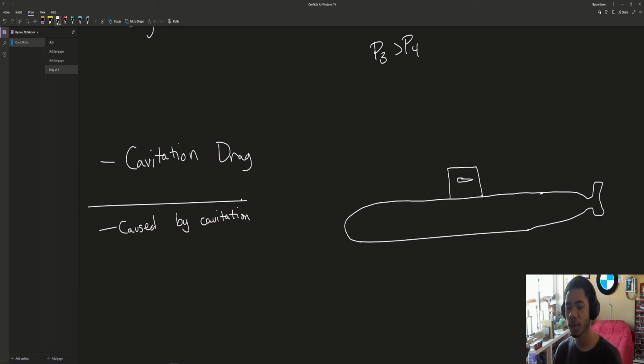Did you know that there are also airfoils on submarines? Because fluid dynamics has the same fundamental properties in water as well. That's why it's called fluid dynamics. It uses a subsonic shape for its body. So anyway, let's go ahead and get to cavitation. So cavitation is, let's say the flow is going over the sub. As the flow goes over the sub, it's going to speed up. And it's possible that the flow on the submarine is moving so fast that the pressure drops to a point to where the water molecules turn to vapor.